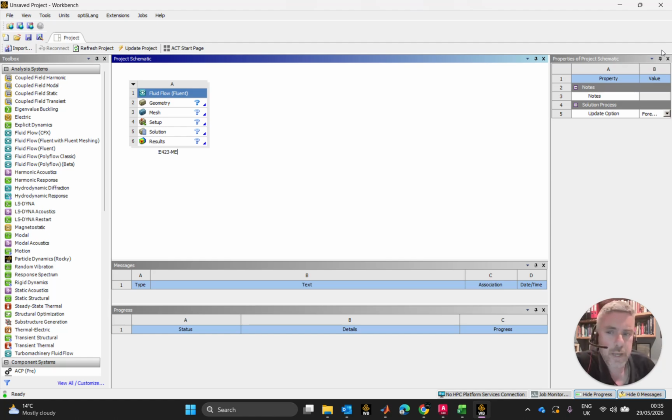So yeah, it's going to be very preliminary at the start, but what it's going to allow us to do is get some sort of a grip on maybe angles of attack, slot spaces between the different flaps, the type of airfoil that might help us, the effect on how the airfoil interfaces with the wheel tire behind it, certain things like that. It would definitely be worthwhile and give us a little bit of insight. So we are going to use it.